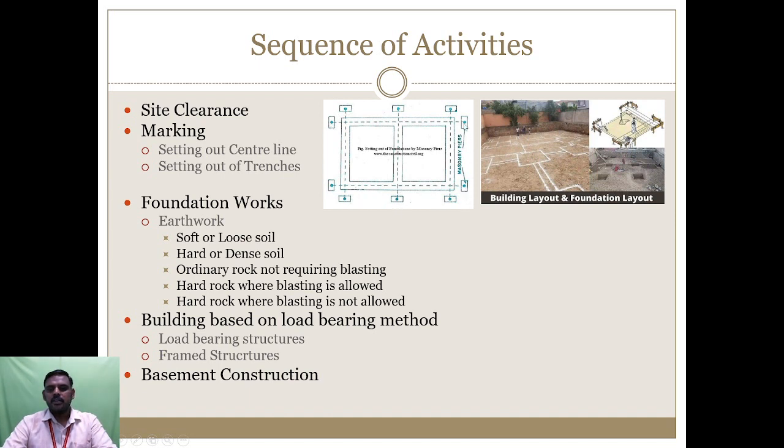It is like a masonry pillar, with the point mentioned on the masonry pillar. It will take a space of 1 meter to 2 meters, which we have to give, so that while we are constructing, we know the reference point to maintain the proper alignment.